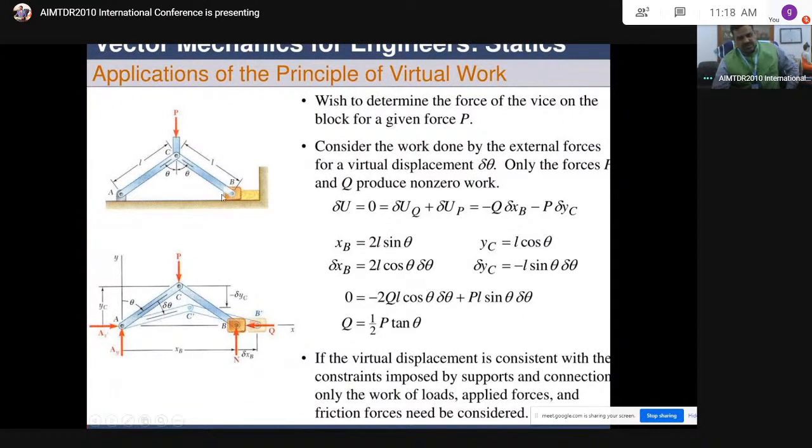This is the piston moving in this direction, a translation degree of freedom. This is the connecting rod, with one end in translation and the other end in rotation. Why? Because the crankshaft is rotating 0 to 360 degrees. At some range, like a coupler, it is oscillating. When moving forward and backward, this coupler makes oscillation, or else it is a pure rotation, 0 to 360 degrees.